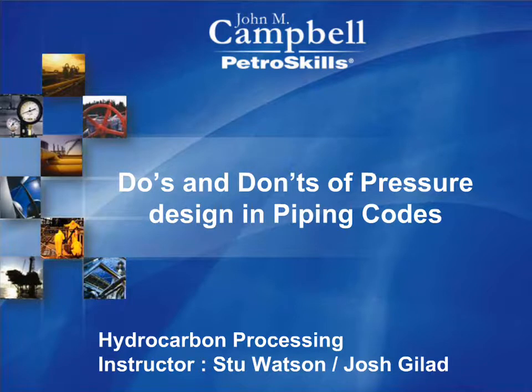In this webinar, we take multiple case scenarios to compare the mechanical design for wall thickness across the industry major piping codes, ASME B31.3, B31.4, and B31.8. In this way, we develop a stronger understanding of allowable stresses, installation environment, corrosion allowances, and where manufacturing tolerances affect the minimum wall thickness. Case studies are based on the same pressure, temperature, and nominal diameter, but consider conventional grade B SMLS versus ERW and materials to high-yield materials.